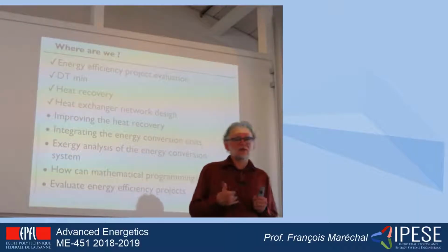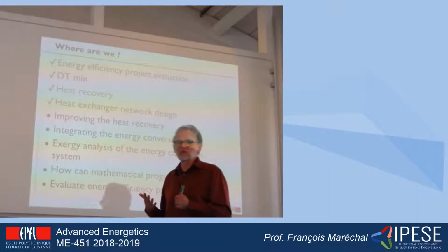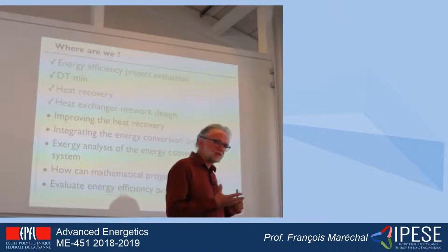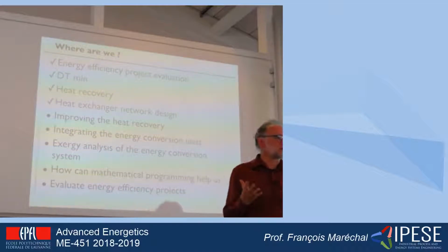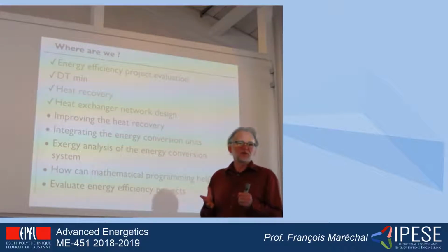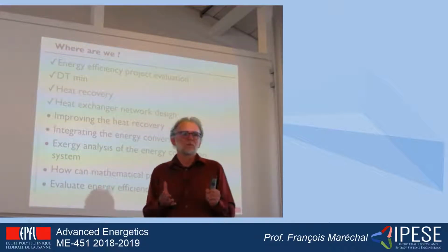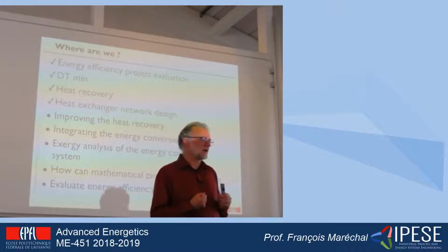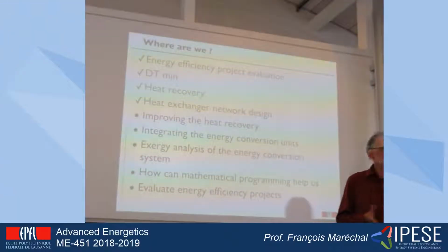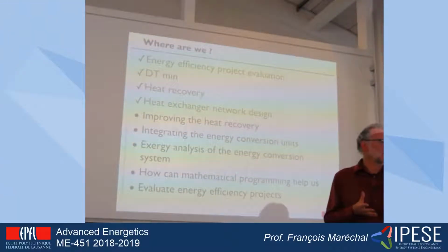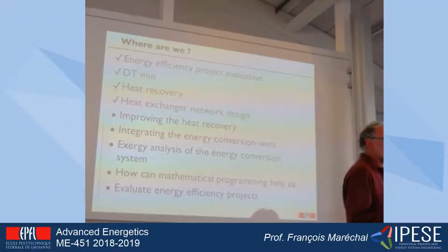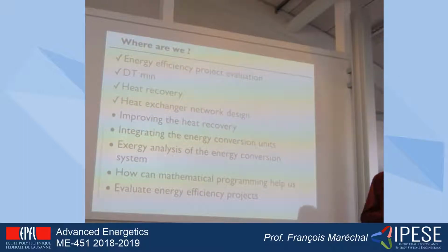Identification of the maximum energy requirement was allowing us to define the pinch point, and the pinch point was dividing the system into subsystems. Above the pinch point, the process is globally asking for heat, which means that the hot streams need to be cooled down by doing heat recovery. And below the pinch point, the system has an excess of heat, which means that the cold streams, the streams that need to be heated, have to be heated by doing heat recovery from hot streams. And I know that I have enough heat in the hot streams to realize it.